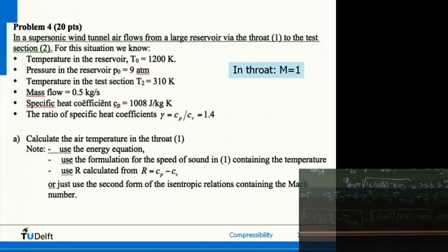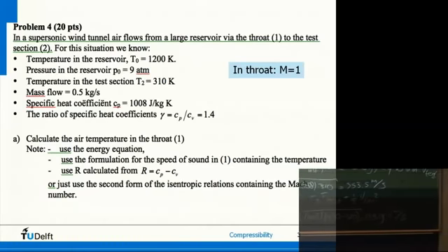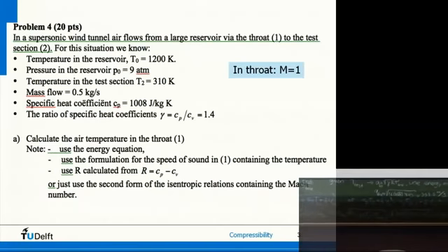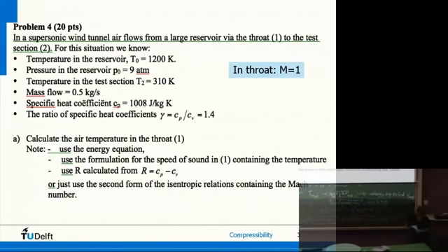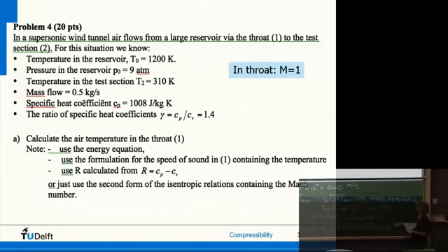So that you can accomplish, right? From 0 in the reservoir, due to this very high pressure, we have very high pressure in the reservoir, we can get to almost 1,400 meters per second. Almost there, because the question was the Mach number, right? So for the Mach number, we have to divide V over A. I'll do it up here.